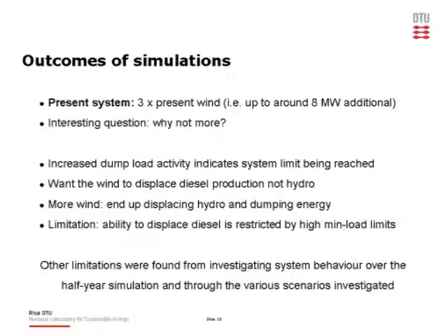So we found other limitations from investigating the system behavior over this 6-month period. And through investigating the various other scenarios, we looked at additional hydro turbines, additional inflow, diesel generators with lower minimum loads, and a mixture of all of those three.